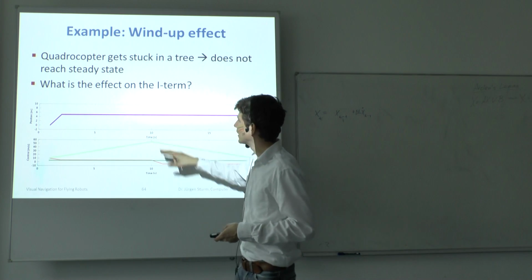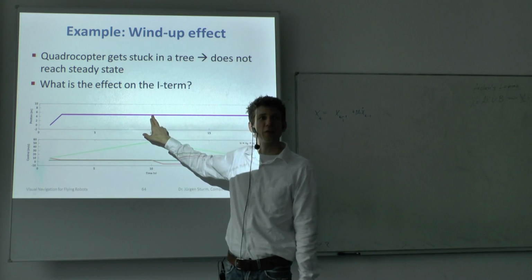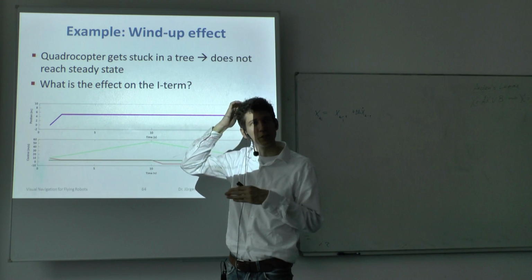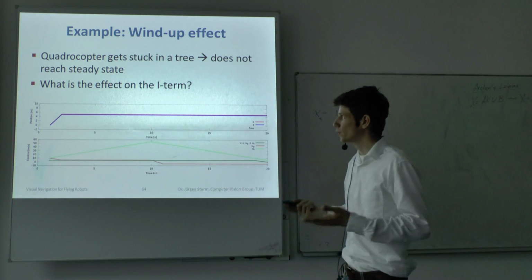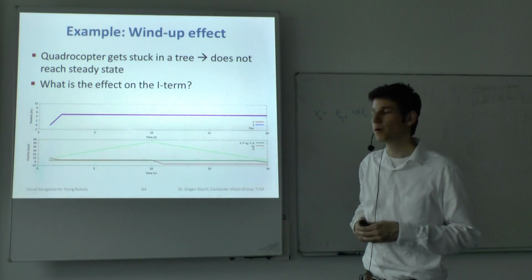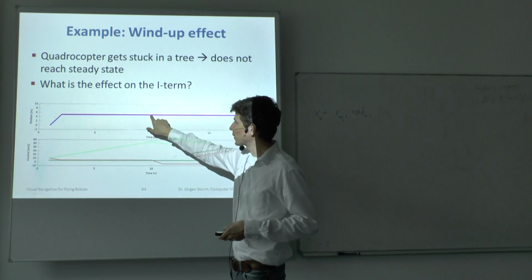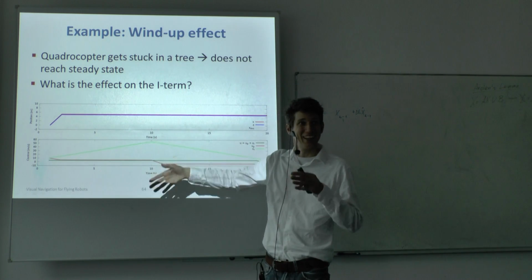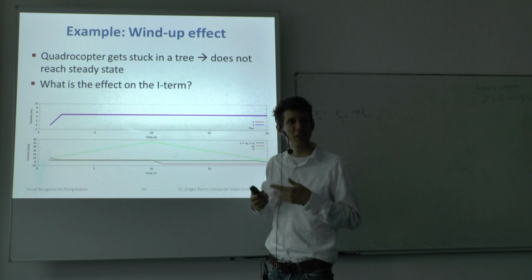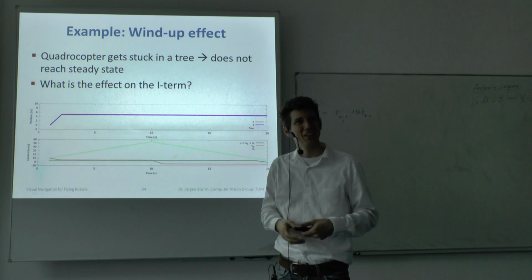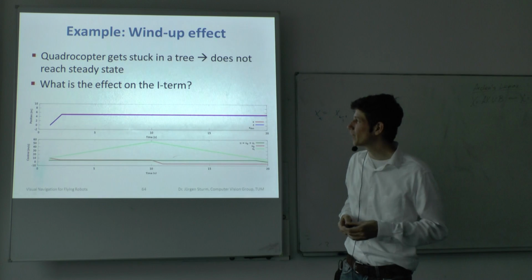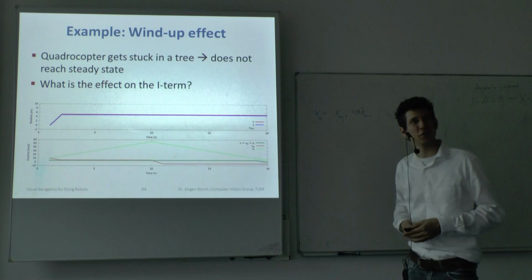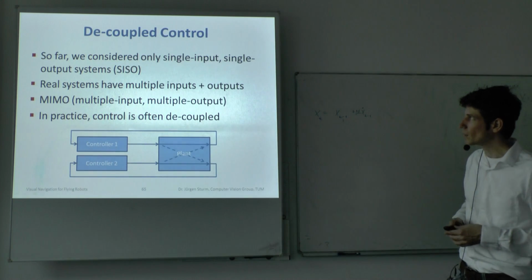Then when we want to fly back, because a higher level module in the architecture realizes that we need to abandon this waypoint and do something else, we specify a different waypoint again at 0, and then this integral part will actually keep us from giving this control, because the integral part still says there is such a large systematic error that we have to correct that your system doesn't move at all, and this is of course not what you want. Good.